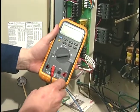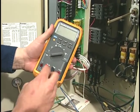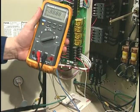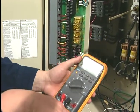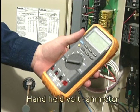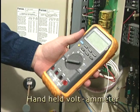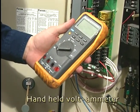However, in practice, readings are usually taken at the motor starter, disconnect switch, or motor control center because these are much safer locations to take readings, and the sacrifice in accuracy is generally very small. A portable handheld volt ammeter is used to take motor voltage and current measurements. The meter may be digital or analog.